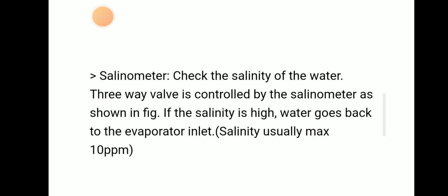And salinometer. Salinometer helps to check the salinity of water. The three-way valve is controlled by the salinometer, as shown in the figure. If salinity is high, water goes back to the evaporator inlet. Salinity is usually a maximum of 10 ppm.